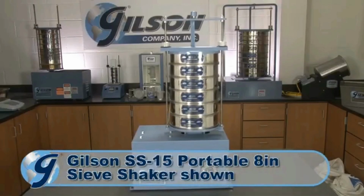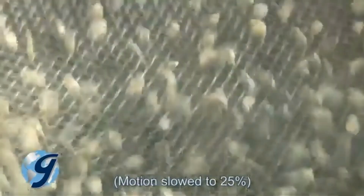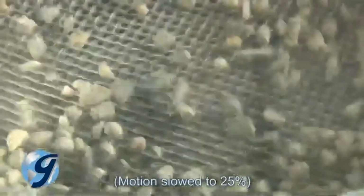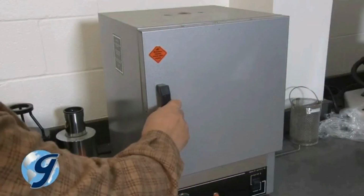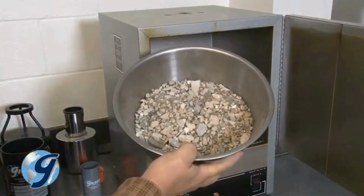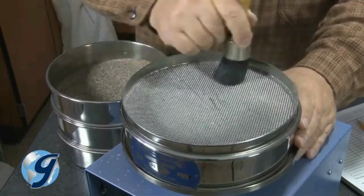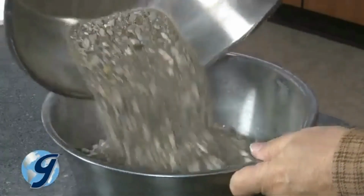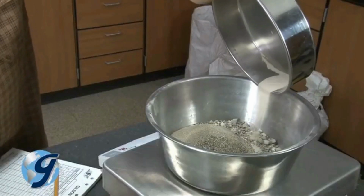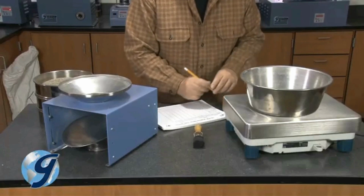A mechanical sieving device to create motion of the particles to bounce, tumble, or otherwise turn so as to present different orientations to the sieving surface. An oven of appropriate size capable of maintaining a uniform temperature of 110 degrees Celsius. A sieve brush, a sample container or pan, a sieve pan, a sieve stack cover, and a way to record and analyze your test findings.